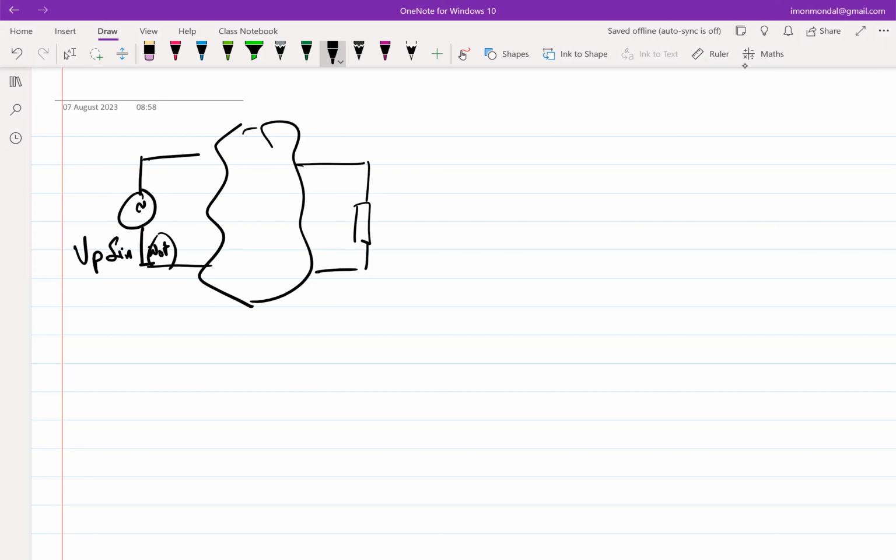Sometimes I have seen students make the mistake that, let's say the constraint on the nonlinear device, in order to honor your small signal approximation, is that the swing across it has to be less than 10 millivolt. Let's say after doing the math, this is what we got. That does not mean Vp has to be less than 10 millivolt. It's obvious when I say it aloud, but you have to ensure you don't make that mistake at the back of your head. So Vp can be different values. It can be smaller than 10, it can be multiple times higher than 10,